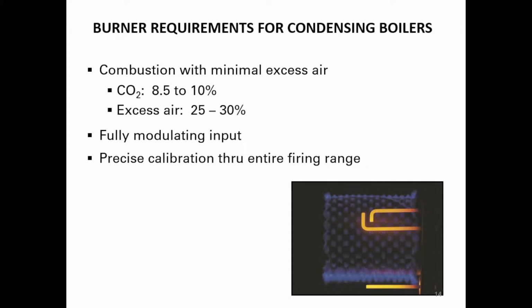So the burner now is set up to drive the best efficiency that the boiler and system are set up to drive. And again, that's trying to keep the combustion discussion down to a minimal amount of slides and discussion. But again, what we're trying to do is get that boiler to condense. From a burner setup standpoint, we set the burner up so that the flame and the combustion products are in the best condition to get the boiler to condense. And now it's a discussion of how do we set up everything else to drive that process forward.